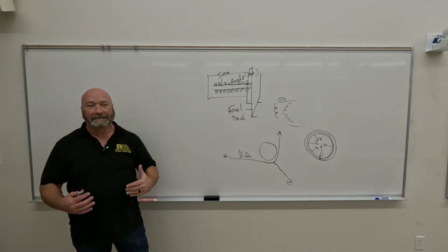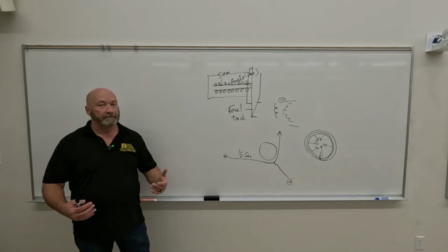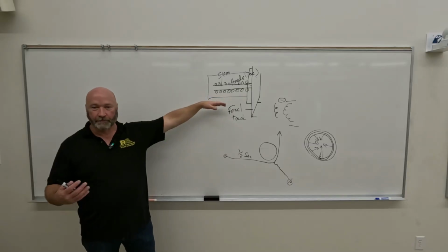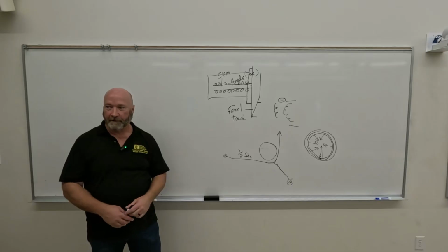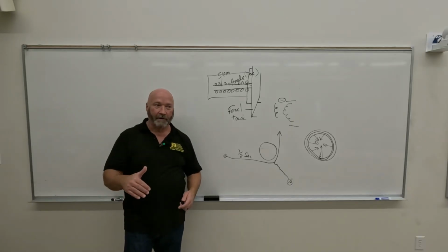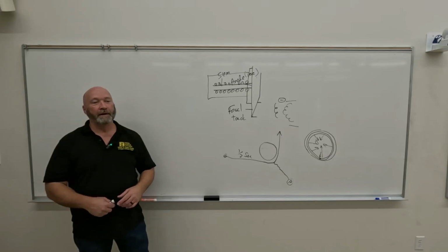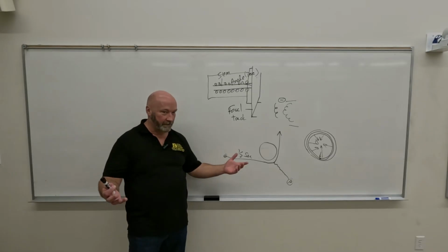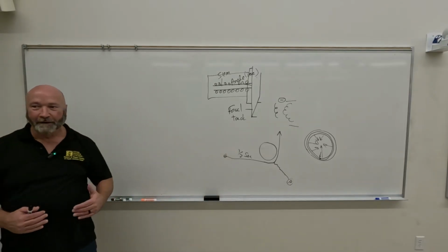It gives you the same stop that feeling. So that's two things. One is that's what it's going to sound like. Number two is, that's how you diagnose your car if you start having a grinding sound while you're driving down the road. If you hit your brakes and it grinds, that's your brakes. You need new brakes. If you're not on your brakes and you're hearing a grinding sound, you need new wheel bearings. So, auto maintenance 101. Bringing a real life thing to you.